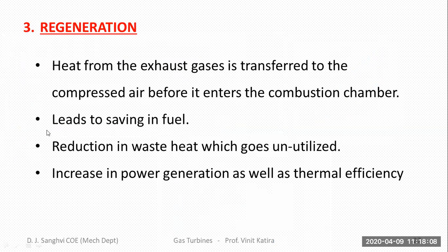Because in the previous case of reheating you were using additional fuel to reheat your products of combustion that leave the first stage turbine, but over here there is no need of additional fuel because you are utilizing the excess energy coming out of the turbine to preheat the compressed air.